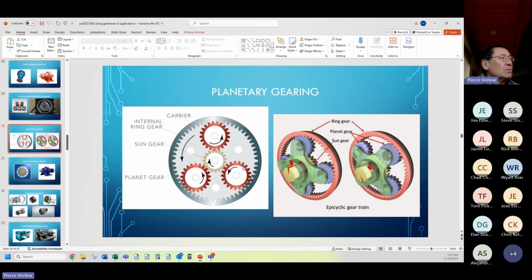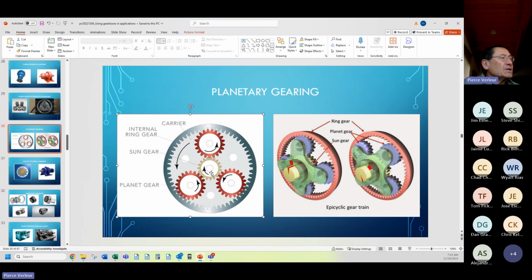And when you reverse the direction, those teeth move across the gaps. That's called backlash. That's a zero motion point in the gearbox output. It can cause a lot of problems because the motor is moving, your encoder is moving on the motor, and there's no movement on the output of the gearbox because you're going through the tooth gap. It causes a lot of issues, which we'll refer to in a moment.